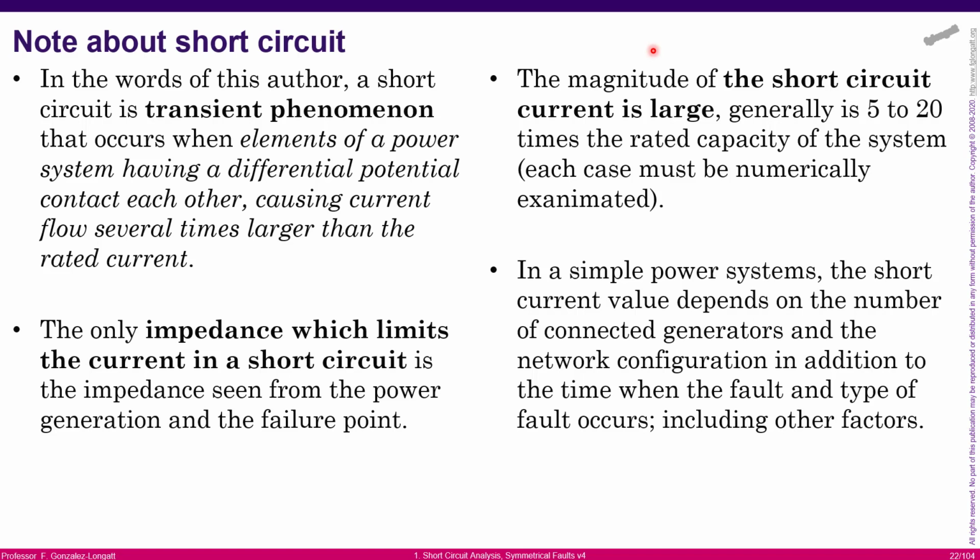Something that is really important is that short circuit condition is a fault. And the impedance that is related in this condition is extremely low, okay? Because the power system is designed to minimize the losses, and as a consequence, resistance and reactance are extremely low, okay? And when you have a fault, when you have a short circuit, you are creating a shunt path for currents. And in this case, the short circuit currents could be very, very large, okay?